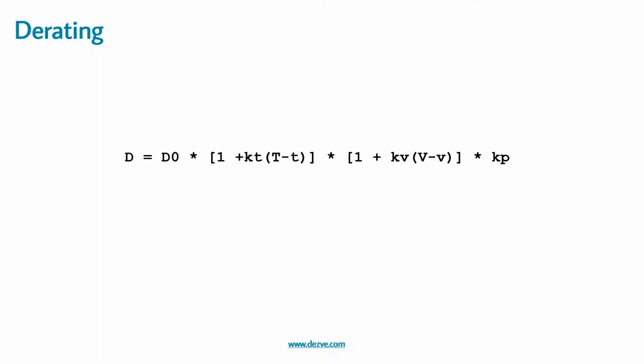Okay. Now in the last lecture we studied slew derate. Slew derate was a term we measured because, in a deep submicron node, we might have measured the slew value across 30, 70 reference thresholds. But then we want to either characterize or provide a number in 10, 90 or 20, 80 format. So we give a derate value which allows the tool to scale that delay value to the respective formats.